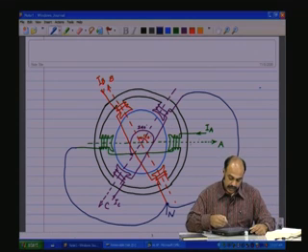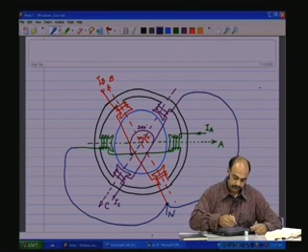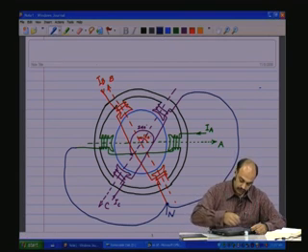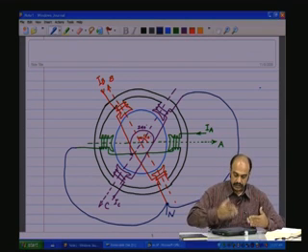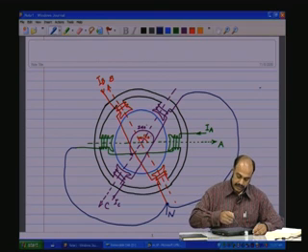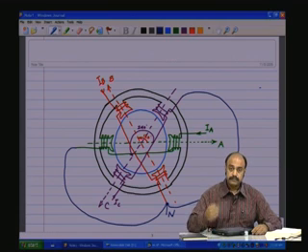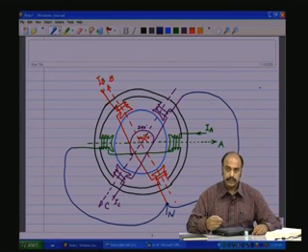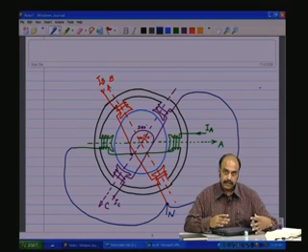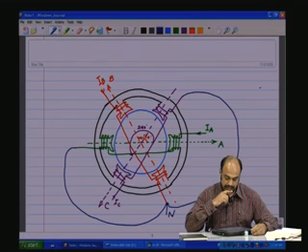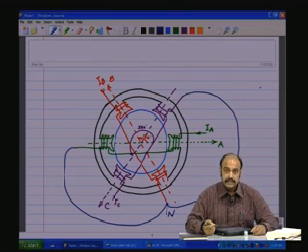flowing. So IA is flowing through the A phase pole, this is stationary, fixed, and IB is flowing through the B phase pole, that is also stationary and fixed in space, 120 degrees shifted with respect to the A phase pole, and IC is flowing through the C phase pole in the C phase axis, and that is also shifted 240 degrees with respect to the A phase, this one, in this manner. So this is a star connected induction motor. The stator coils are star connected with the currents IA, IB, IC flowing in this manner.